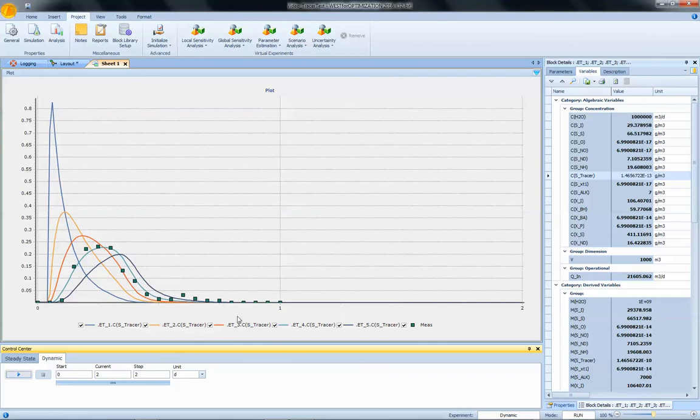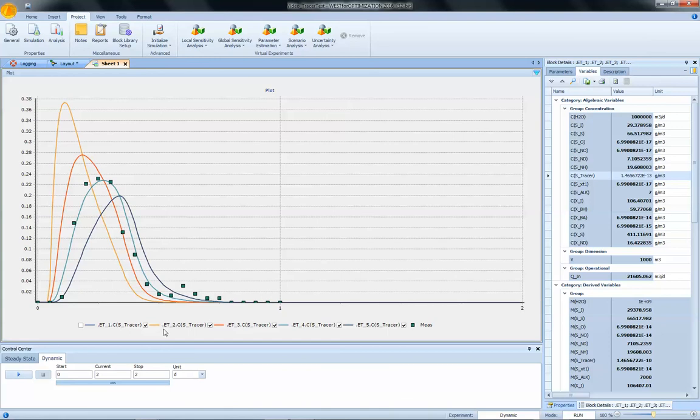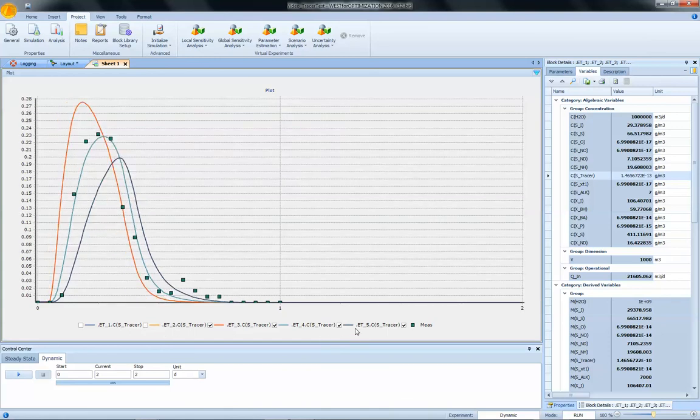So how can I interpret the results of the simulation? I can certainly turn this off and probably this one as well. So the conclusion would be that my real scale tank behaves pretty much like a 3 tank in series. You see here, this is the curve. These are my measurements between 3 and 4 compartments, like 4 compartments in series.